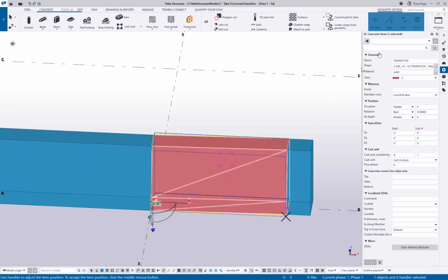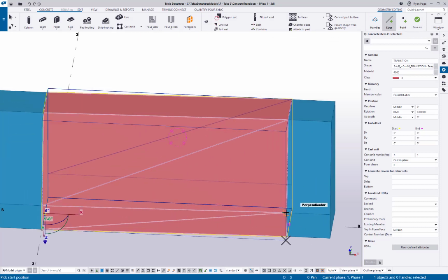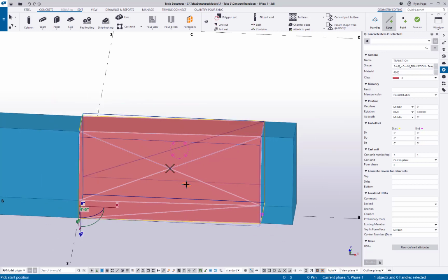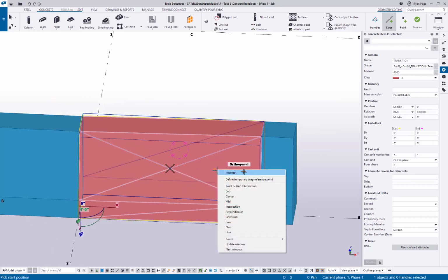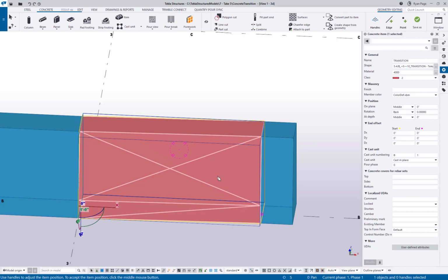Now, keep in mind, you can go and make a crisscross and separate this into 4 separate triangles, but when you do so, you cannot cross over an edge like this that is already established. Notice when I snap here, I give it a red line, but if I snap to the center point here, then I can create that and then continue that from the other side. So there's a tip right there. Make sure you don't get frustrated trying to cross over an edge you've already created, because you won't be able to.